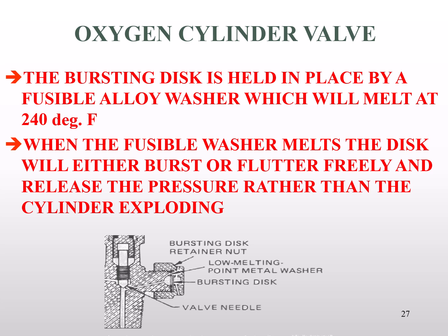This is a little better illustration of that particular circuit in that bottle. Generally, these discs would melt at around 240 degrees Fahrenheit. Once it melts, the oxygen can discharge at a reasonable rate, lowering the internal pressure of the bottle, keeping it safe. An oxygen bottle that explodes is simply a bomb, and the fragments of steel will penetrate through block walls. So this is a much safer way to manage these bottles in case they're overheated and overpressure.